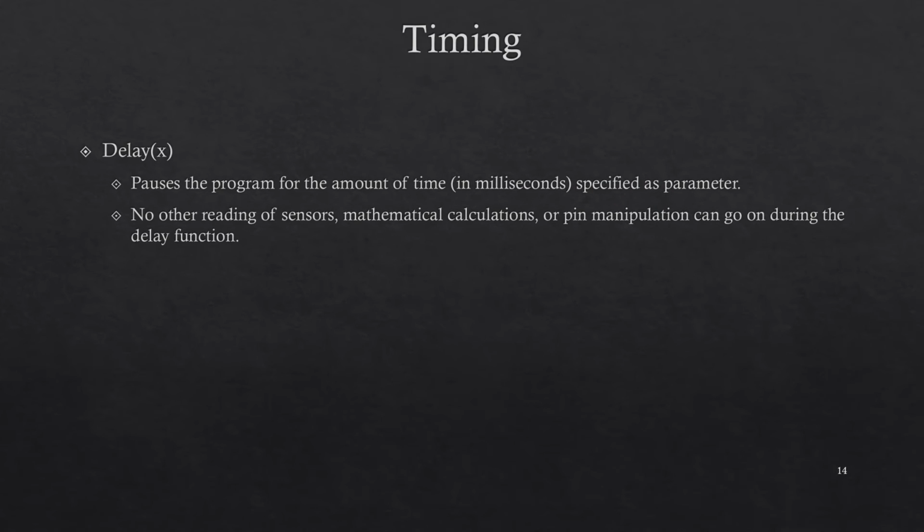Now let's talk about timing. You have used the delay function, which takes an argument in between two parentheses in milliseconds. This function pauses the program for the amount of time you have defined in between two parentheses. While it is easy to create a blinking LED, for example, with the delay function, and many short sketches, for example the debouncing problem, the use of the delay function in a sketch has a significant drawback.